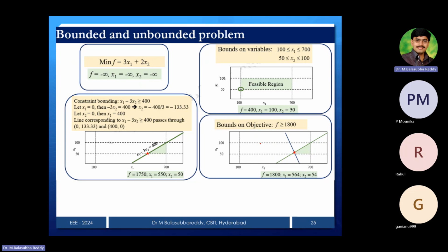Generator 1 is 3, generator 2 is 7 megawatt, but let us assume that the capacity of generator 2 is only 0 to 5 and generator 1 also 0 to 5, but the value you got is 7 megawatt. That is the problem. We need to check whether it is within the boundary or not.